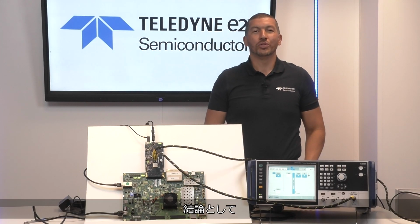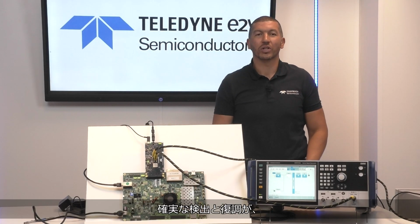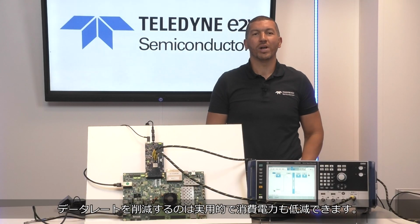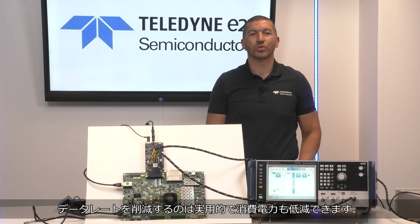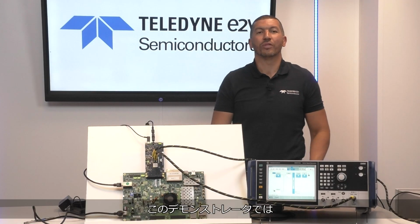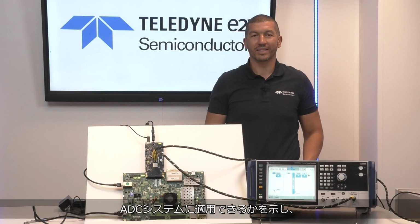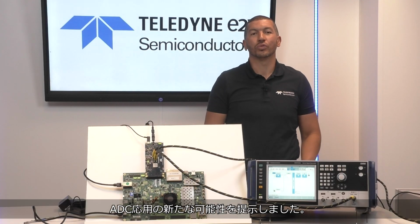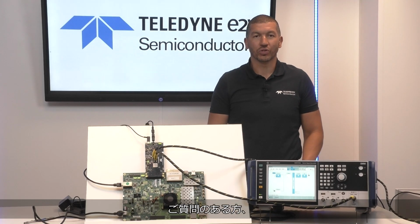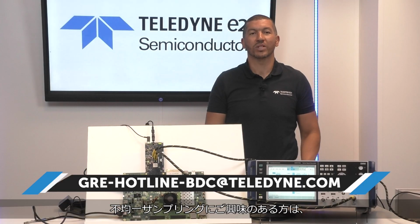As a conclusion, our results show that non-uniform sampling enables robust detection and demodulation even at low SNRs. It's a practical way to reduce data rates and power consumption while maintaining signal fidelity. This demonstrator provides a concrete example of how non-uniform sampling can be applied in ADC systems and opens the door to future ADC usage.